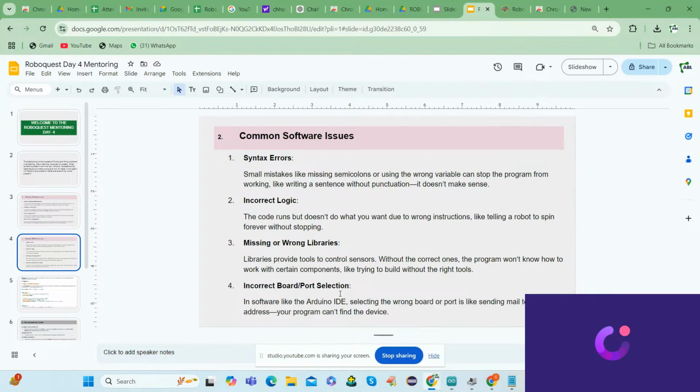After clicking on Tools, first you have to select your Arduino Uno, because in your controller I used the Arduino Uno, so that's why you have to select the Arduino Uno. After selecting Arduino Uno, you have to select the port. Once you connect your USB cable to the computer, it will show COM4 or COM3 or COM2. That is called the port for your computer. Done?